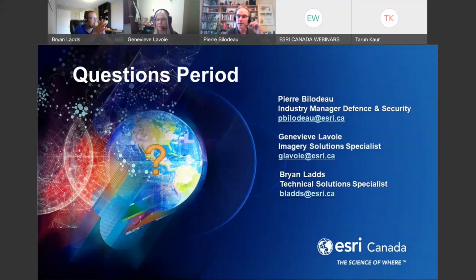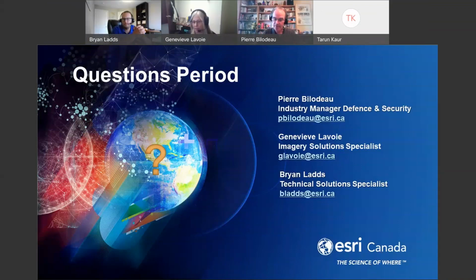Thank you, Brian. The next question I think Geneviève, maybe you can address is, do we need to specify the geoid height above the imagery ellipsoid difference for the output coordinate system? Not necessarily. When you use Drone to Map, it's built on top of Pix4D, so a lot of the settings are the same. So yes, you can specify your geoid, but you can also just input your GCPs, and the GCPs will do the correction, and your product will end up in the right place.